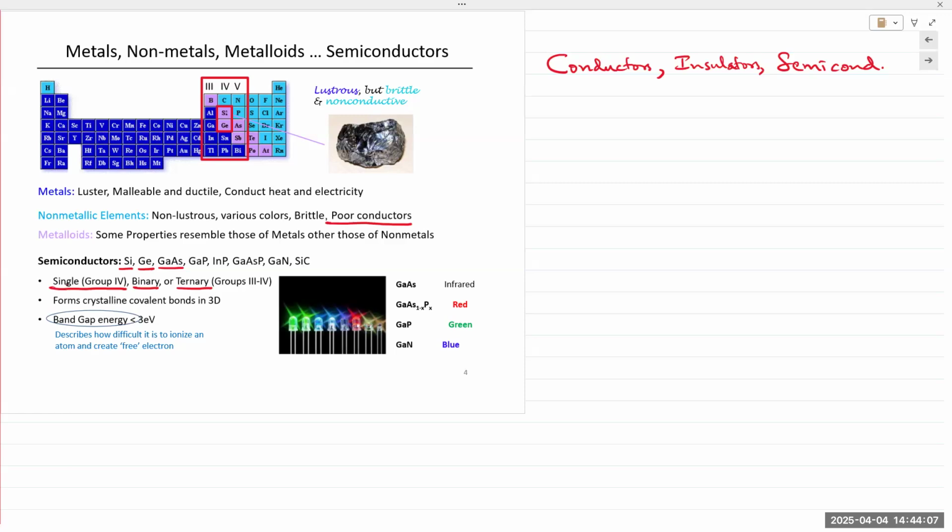One interesting thing that happens with some semiconductors is that they release a little bit of heat, but they also release a majority of their energy as light. So if you build diodes using gallium arsenide, gallium phosphide, or gallium arsenide phosphide, they emit light in addition to a little bit of heat, and hence they are known as light emitting diodes, LEDs. Depending on the material that we use, we can have different colors for LEDs. And that should also be part of your lab kit.